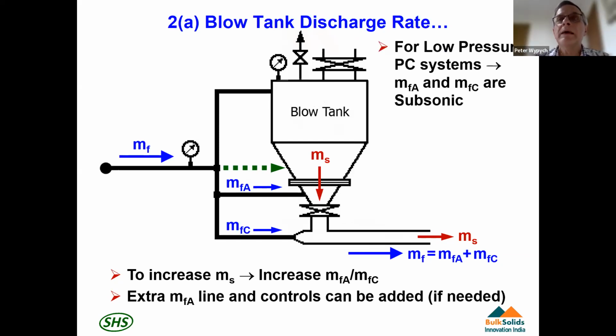That's very important. So for low pressure systems, my experience is in India, where most of the pneumatic conveying systems, the positive pressure systems, are low pressure. Transport air compressors, sort of maximum 200 to 300 kPa. I call that low pressure. Most of the systems in Australia are high pressure, 600, 700 kPa. And in China too, they tend to be 500 to up to 700 kPa gauge compressors. Anyway, there are reasons for that, and I won't go into the detail of it.